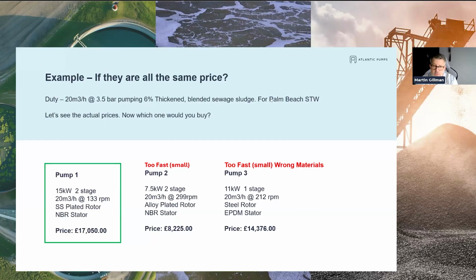It's not uncommon for works, treatment works, pumping stations near the coast to have a certain amount of salt water involved. So we've got a stainless steel plated rotor here, so we're going to have corrosion resistance. And I did that as a little bit of a sly one, but it's important that you understand that it's not just the performance, the materials matter.